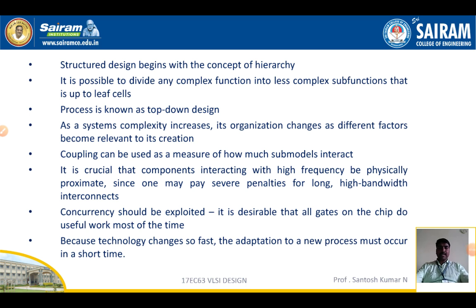Illustration of design process. Structured design begins with the concept of hierarchy. The concept of hierarchy indicates a top-down design approach. That is, a complex function is subdivided into subfunctions, and then the subfunctions are divided into leaf cells. As system complexity increases, its organization changes as different factors become relevant to its creation.